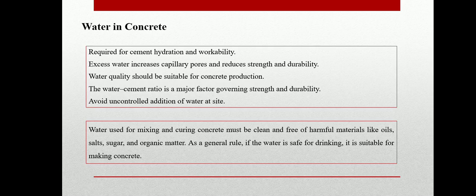Any water beyond what is needed for hydration ends up creating capillary pores within the hardened concrete once it evaporates. And this directly reduces both strength and durability. This relationship is captured in what we call the water cement ratio. And I want you to remember this term because it comes up again and again. It's one of the single most important factors governing the strength and durability of concrete.